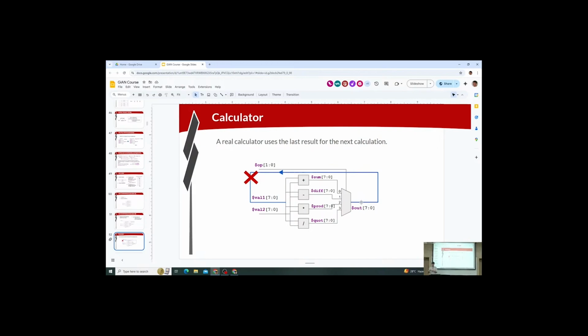So it may transition several times before it actually settles on the proper value, the stable value. That value is going to propagate around. If we just let all of that random transitioning propagate through, val1 is going to change, that new change is going to propagate through, and our circuit's not stable. So we need to carefully sequence the circuit by introducing a clock.